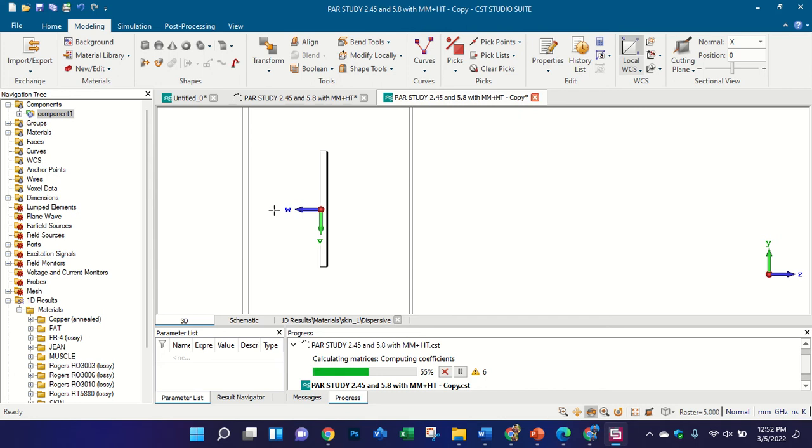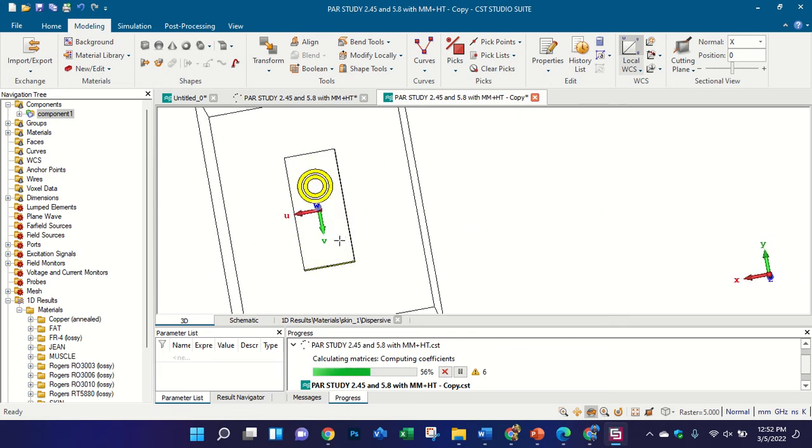The distance of the skin, fat and muscle tissues depends on the structure of the antenna. Suppose I have an antenna and I am using a full ground plane behind the antenna, behind the substrate. Then if you have copper on the complete surface of the antenna, it will not affect your human tissues much, even if it is closer and closer.